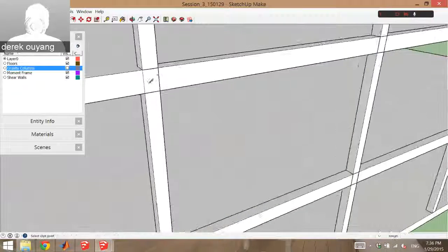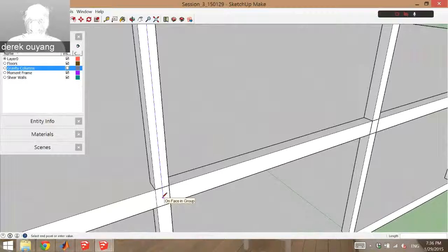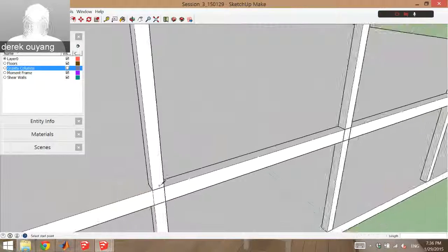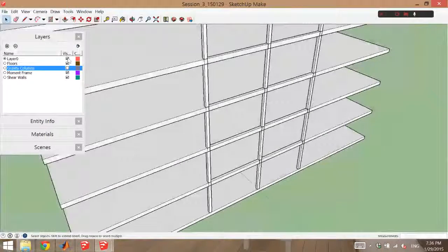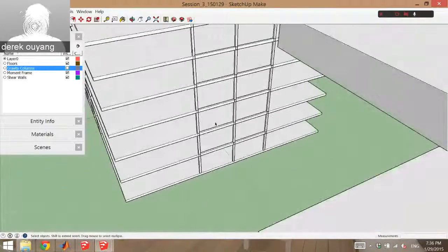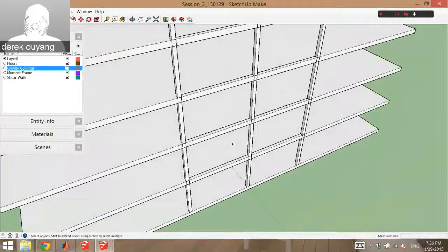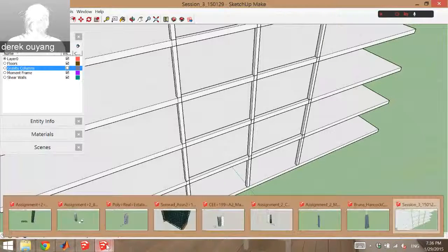Yeah, so technically your grid point will be right here, and it'll go to right here. But for the purposes of measurement, I'm just going to use the floor to floor height. You probably won't model it to that detail in MASTAN for 183, but technically, what you should be doing when you model a beam in MASTAN is, let's say this is a 15-foot beam, and you're going to assign it some stiffness and some properties.